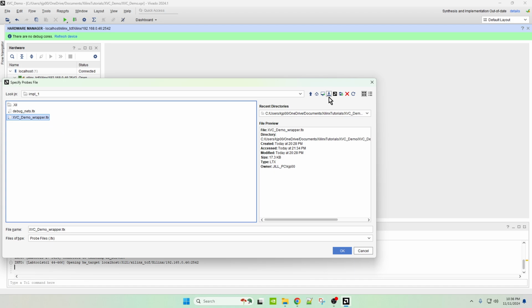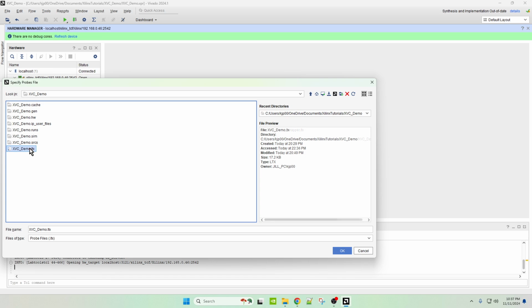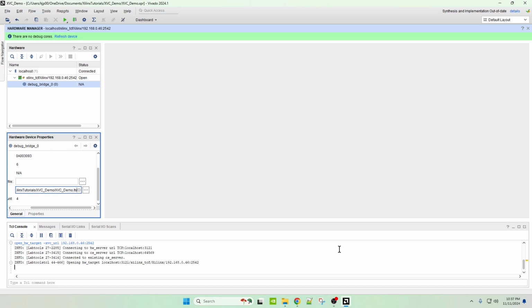And what I've done is I've modified that, because I have no idea why this happens, but for whatever reason, Vivado IP Integrator has a mind of its own when it comes to naming these debug probes in the waveform thing. So I just went ahead and named the ports what I wanted them to be named, so we're just going to use that. But it is automatically generated under that runs implementation folder. And we just hit enter.